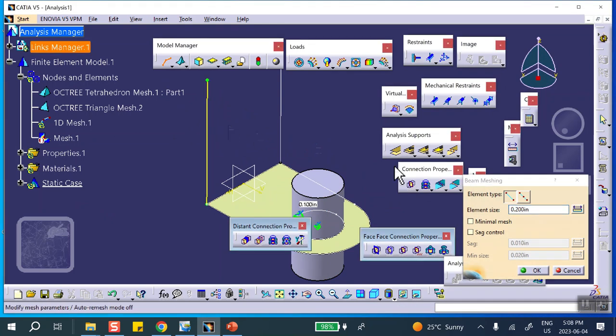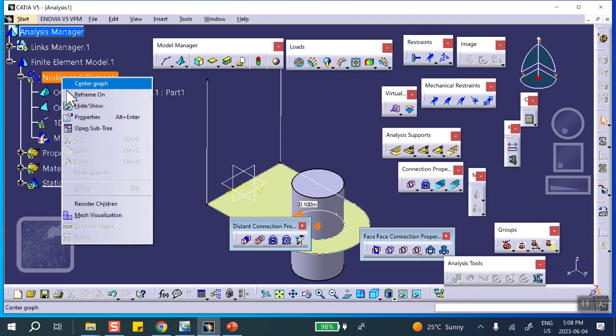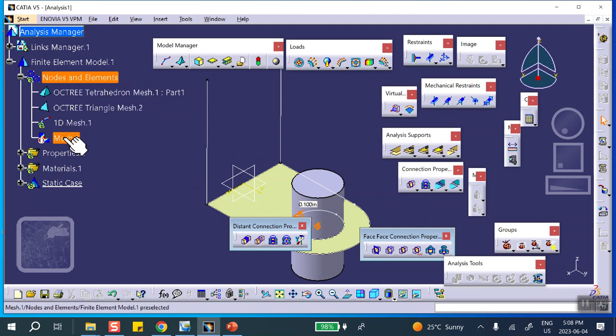This was 3 inches, and why don't we take 1 inch, well actually let me make 0.1, for a reason that I want to show you later on. 0.2, so that's going to be about 15 elements through that length. Let me make it 0.2. Okay, good. You say okay, and if you look at it, you see that that's also there.